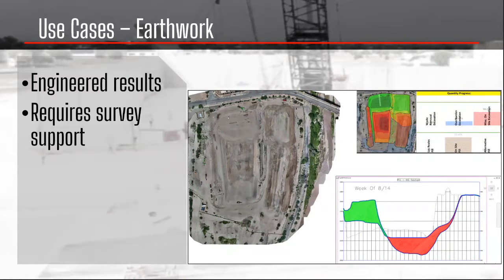And so in this case, we were able to go and fly this project immediately after Earthworks and use volumetrics and cut fill analysis to determine where exactly they have been digging, how much they've removed, which, once you know how much they've removed, you know how much they should be appropriately billing us, and to know the accuracy of it all.